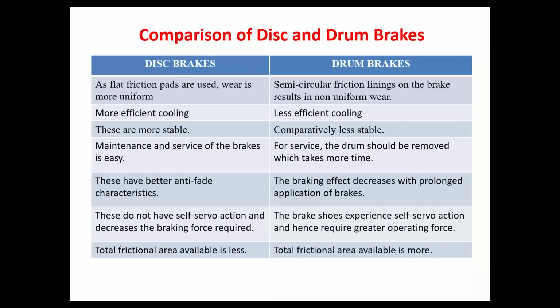If you are driving the vehicle in a hilly station, wherein continuously you should keep on using the brakes, in such cases disc brakes are much preferred over drum brakes. So this is the second main comparison, wherein in the first 2 points disc brakes are far better compared to drum brakes. The third is stability.